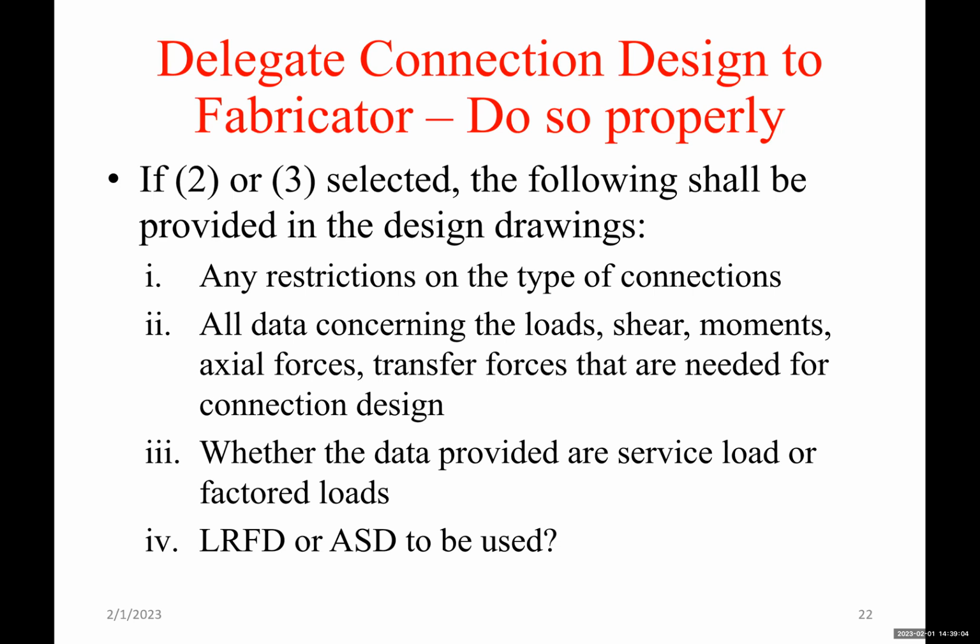But for example, if it's not in California, you can have that braced frame geometry with a table showing all the dimensions that you need, and also all the forces that you need for different types of braced frame connections. This way, the fabricator has the geometry and has the forces, and let them design. Welded, bolted, if they need, of course, any different configuration.